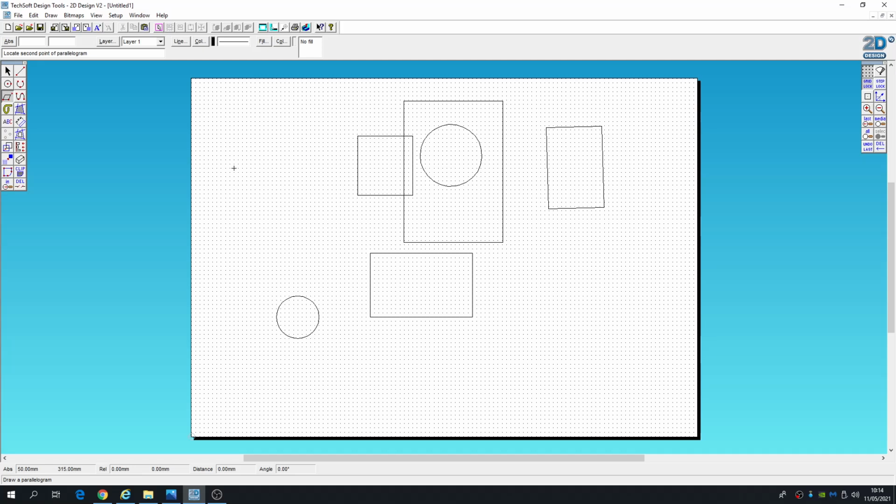So you would select a spot, go across, and you can make your parallelogram if that's what you've selected. Or if you select triangle, then you select a spot, and then the top, and there's your triangle. So you click and hold, and you stretch out, and you release, and you click again to indicate that that's your baseline.